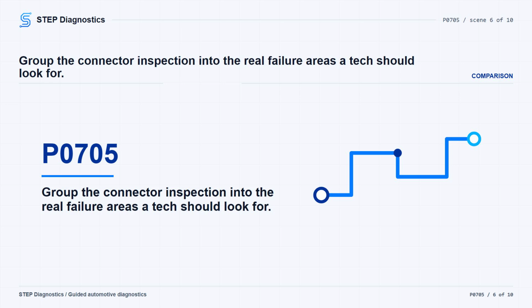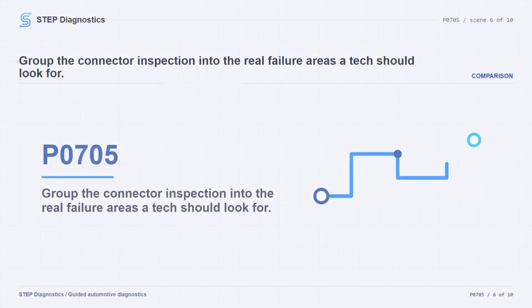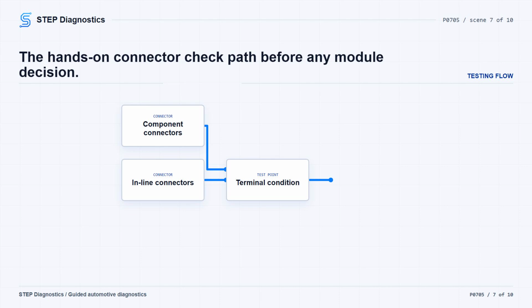Look for poor connector installation, damaged locks, corrosion, water intrusion, damaged weather seals if used, bent terminals, overheated or discolored terminals from a poor connection, and terminals pushed back in the cavity. Then perform a terminal drag test on each connector terminal to check terminal tension.